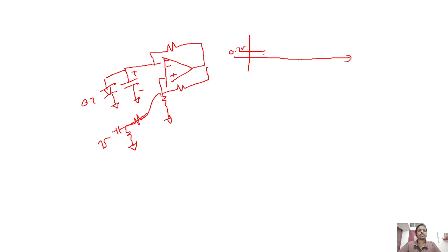Whenever there is a trigger, the capacitor voltage will slowly decrement to beta V naught, and when it reaches beta V naught, the output will again change, say +2 to minus or -2 to plus, it must be +2 to minus, right? Then it will slowly integrate back to 0.7. So I think this is the time being mentioned there.